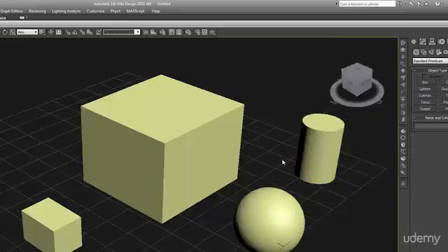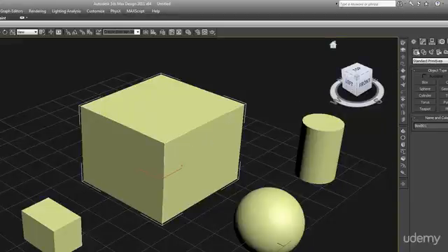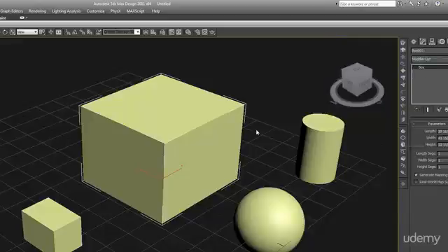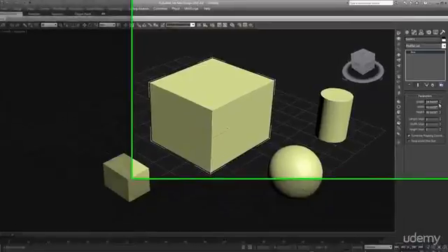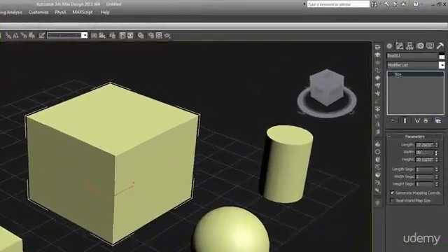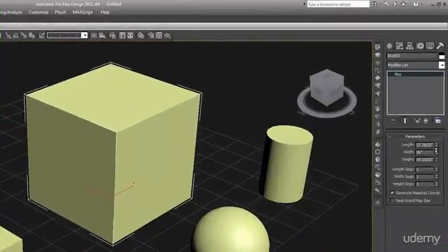Okay, so you can go through all your standard primitives, but remember, if you click on the box and then go back into your Modify tab, which is this one, Modify, then you can go back to all those parameters that you previously set, and you can adjust them more. Let me just show you what some of these things do. Some of these are self-explanatory: length, width, height.